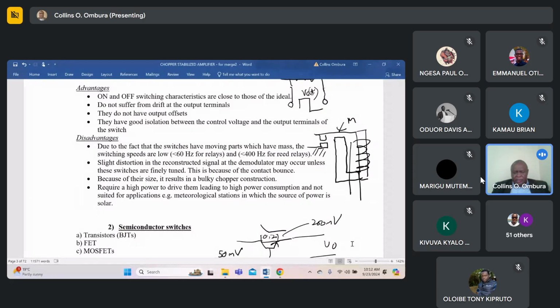And I told you to go and revise your telecoms, revise the sinc function, because with the sinc function we're able to get the frequency spectrum of rectangular waveforms, and how the amplitude of the spectrum changes as we change the width of the pulse. When the width of the pulse is almost zero, which we call the delta function, then the spectrum is linear from the lowest frequency. The amplitude is the same from the lowest frequency to the highest frequency component.